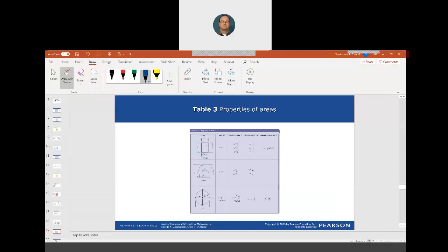In the formulas, BH cubed, HB cubed, these terms are turned around, but if B and H are the same, if it's square, we don't have to worry about which is our stiffer axis. A real life example of this is we actually had to put piles into a circular foundation driven to bedrock.